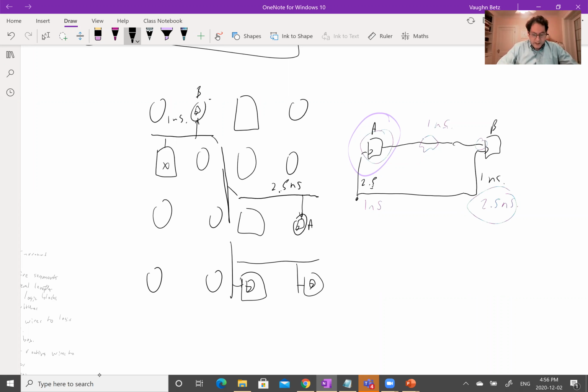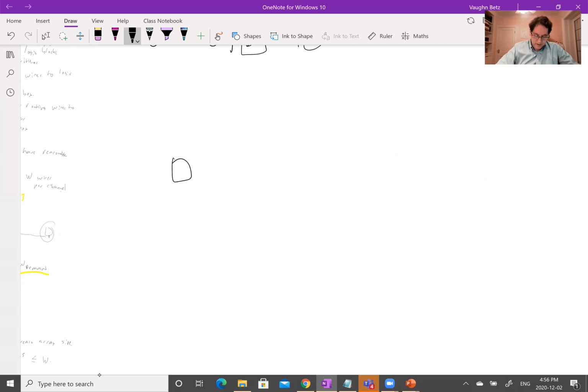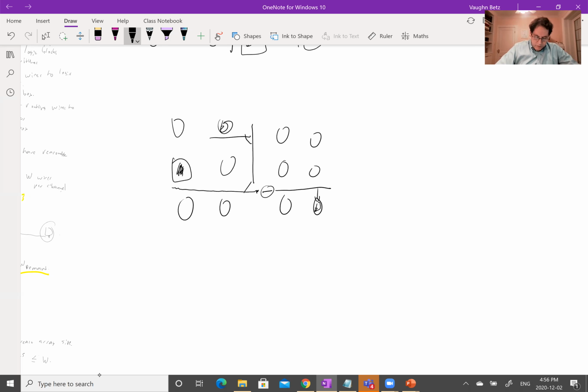Now I can try to make a low skew routing algorithm. So if I changed my CAD tools to do that, let's just go down here and draw this case again. Okay, so here's my clock source, and it's trying to go to a few destinations. Let's just say there's a register here, and there's a register here. So one is far, one is near. With a low skew routing algorithm, the router should actually try to maybe go to some medium point here, and then take a routing switch to get onto another wire, go in there, and take a different routing switch, go up here, maybe take a routing switch and go in there. Okay, and that's closer. If you trace out the delays here, they look closer. So maybe this one is now 1.5 nanoseconds, so it got slower. And maybe this one was 1.3 nanoseconds. So they're definitely closer. It's lower skew.